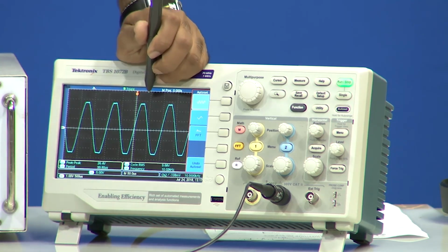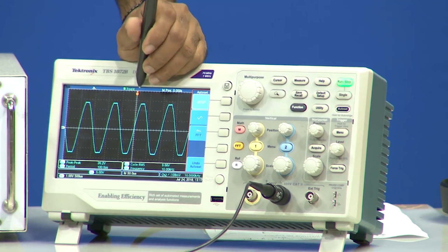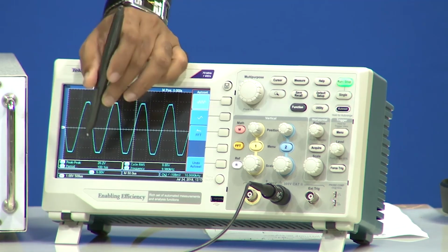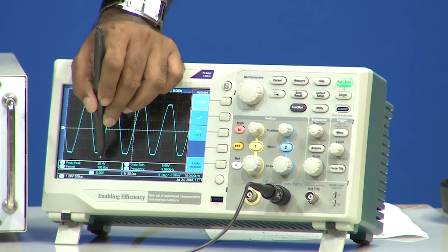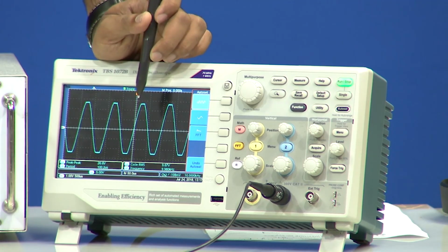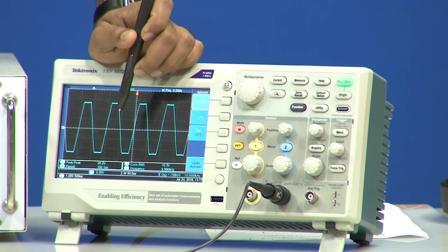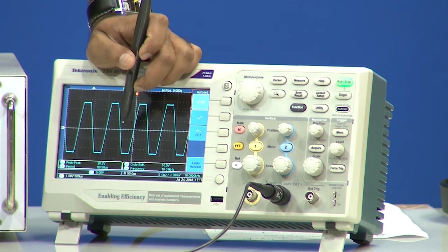Now, it is around 13 volt, so 13 volt peak to peak. That is around 6.5 volt input voltage where you are getting the clipping action. The peak to peak voltage here is 26.4 volt. So, you are seeing the clipping clearly. If I increase it further, you can see that the saturation effect becomes more profound and more expressed, correct.